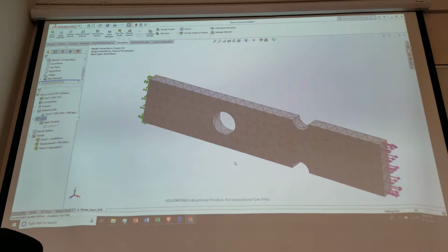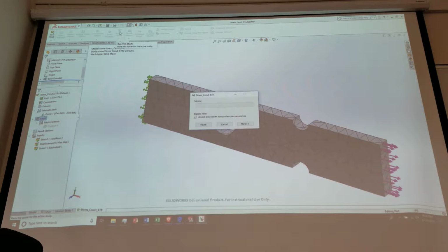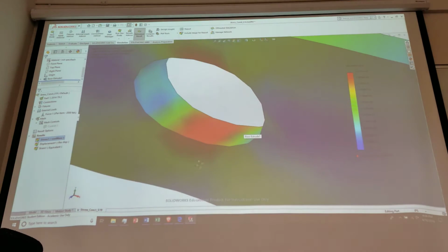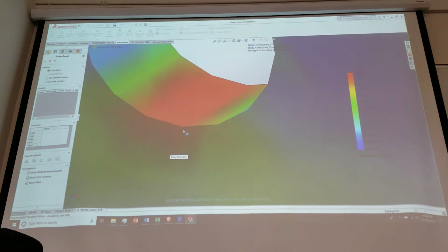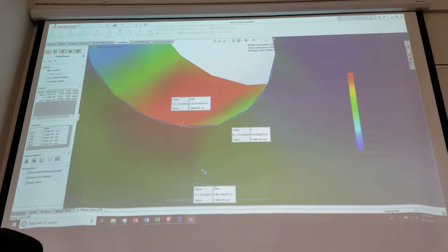So now if I run this, of course I see areas in here that are unhappy, and I can tell if I go do my probe thing here that I've got 1 node in there, right? And the next node, you can kind of see it as it runs down to this edge here and over to here, right? I mean, I have a very high stress gradient. It goes from being 29 to 21, so it changes by about 30%, right? And that's in a node, right?